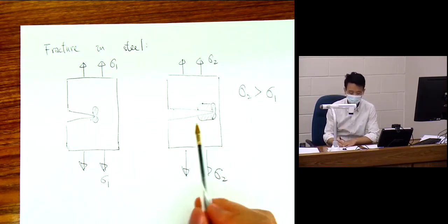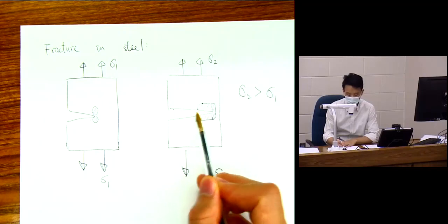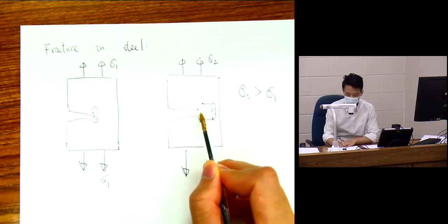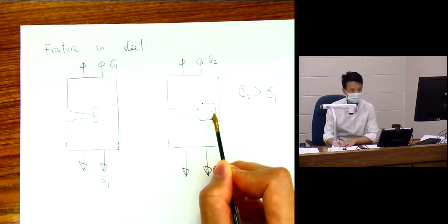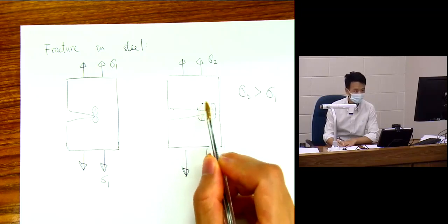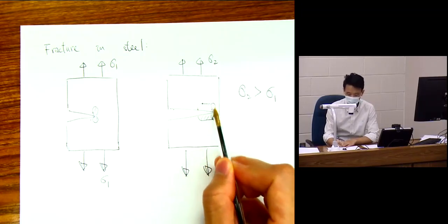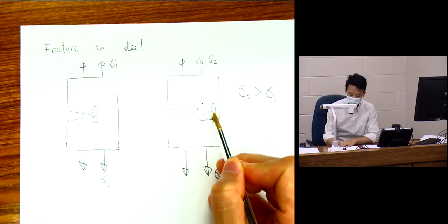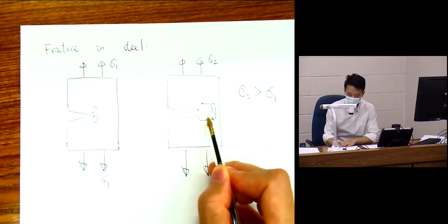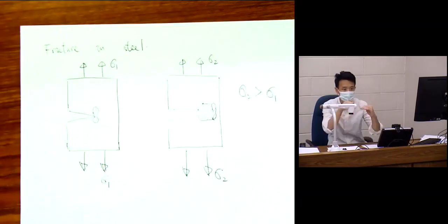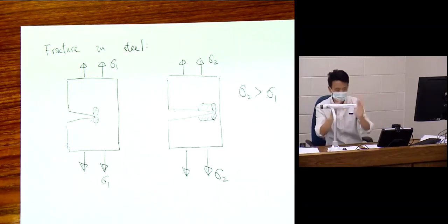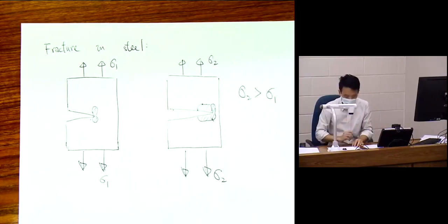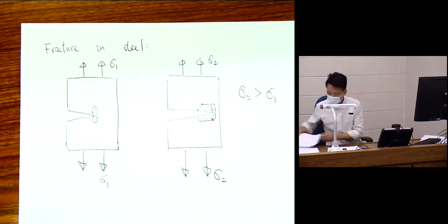The energy is enough to make the crack advance, so it advances, let's say to this position. Now, because this is the original position, all this path that the crack tip has crossed is all plastically deformed. So that zone now extends to here. This is the current front of the crack. But these are all already plastically deformed because the crack just passed through, so it left behind that plastic zone. Plastic deformation is permanent, so it stayed there. This is the situation I was talking about.